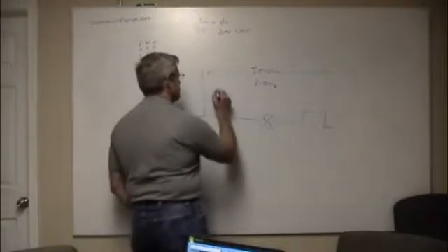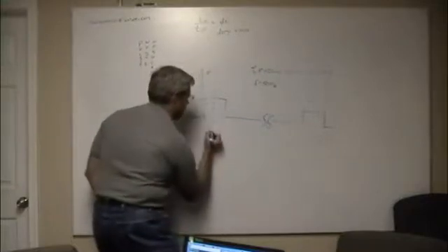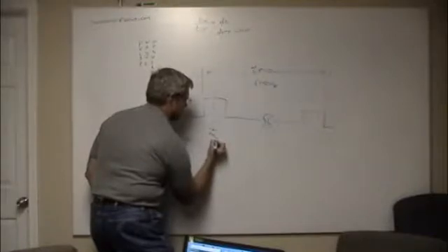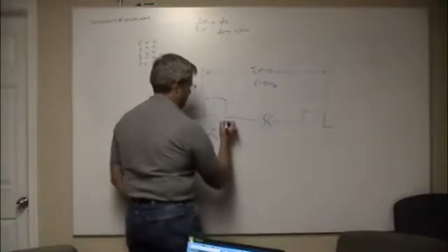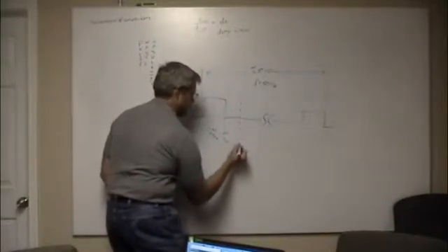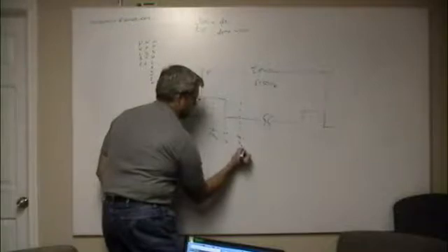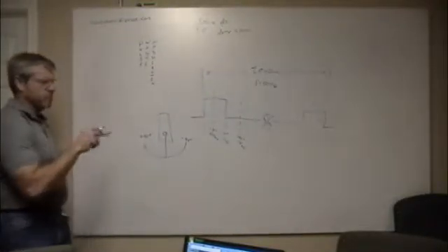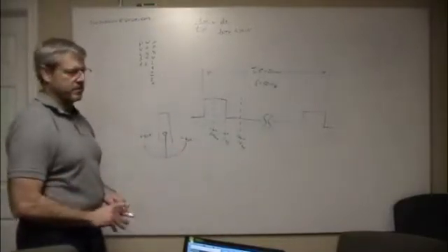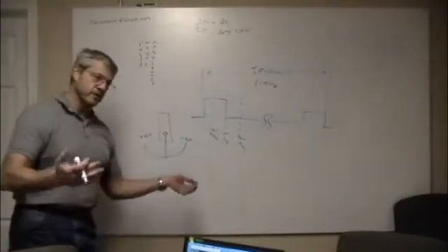Minus 90 degrees is 0.5 milliseconds. 0 degrees is at 1 millisecond. And plus 90 degrees is at 1.5 milliseconds. I think that's right. It might be 1, 1.5, and 2. I've got it all in my documentation. Look it up for your servo motor. But most of them are like this. So that's why you would want to do PWM.